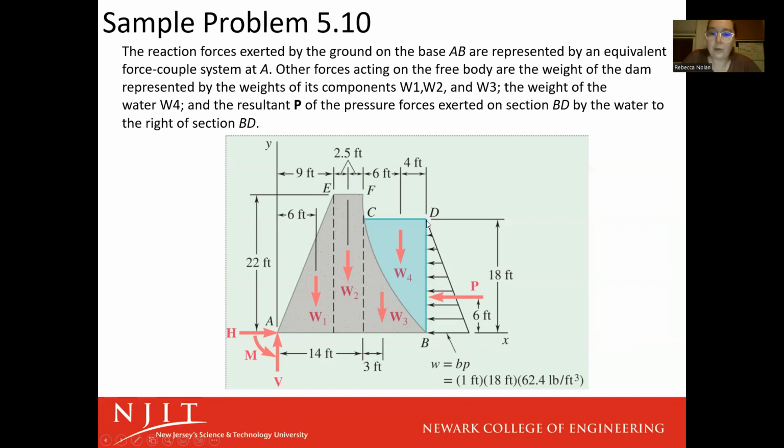But so we're starting from a lesser amount of pressure. We'll find out in your fluid dynamics class probably that pressure and depth have a linear relationship. So we're going to have a linear distributed load going down. I think I just wanted to show this problem too, to show how many elements. So this is a concrete base, right? So it's going to be hard for this to rotate. So there is going to be that constraint, that moment constraint introduced as well.